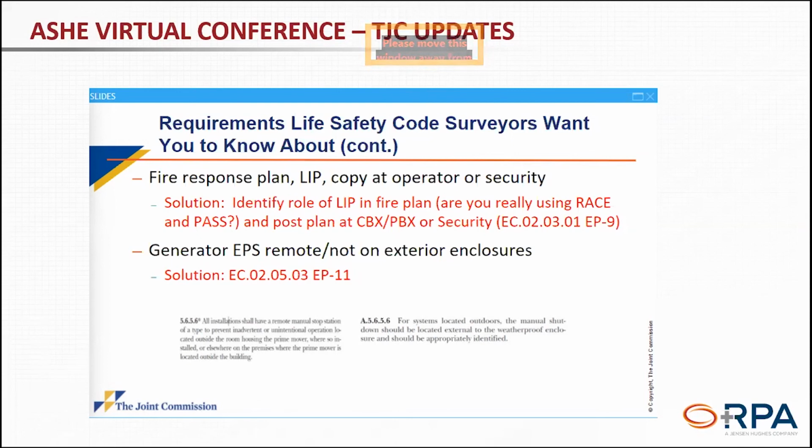Generator remote stop buttons. Those are still a hot button. No pun intended there. But make sure you have them, and they're not immediately at the generator. They need to be outside of the enclosure. And if it's an exterior enclosure, they need to be outside of that also. I don't know exactly what that means for your particular facility, but it just means it has to be well away. And there's some further information in those 2 sections under EC.02.05.03 EP 11.